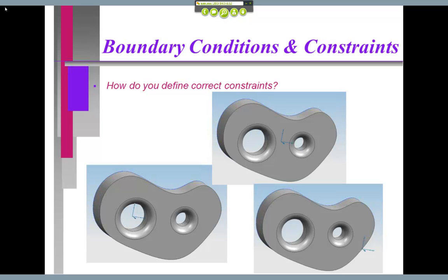Well, it is if you put all of the other loads on top of this thing, loads in the back and everything else, because those loads are going to want to bring this thing up and forward, okay? But it's a static analysis. You have to fix it so this thing is not just drifting through space. If you don't lock it down so this thing can rotate around an axis, or translate along an axis, you're never going to get it to solve. It'll just go crunch, crunch, run, run, run. You have to somehow hold this thing down.